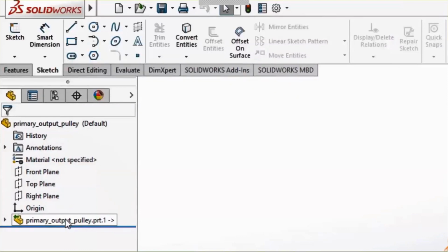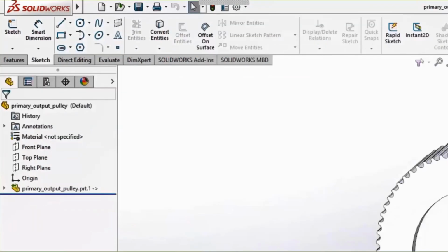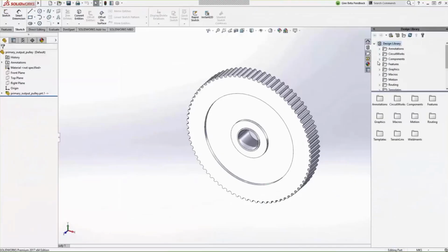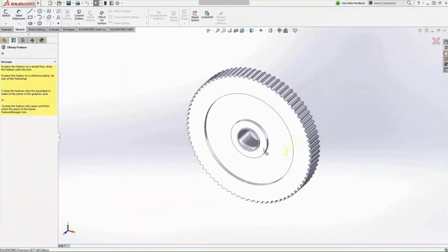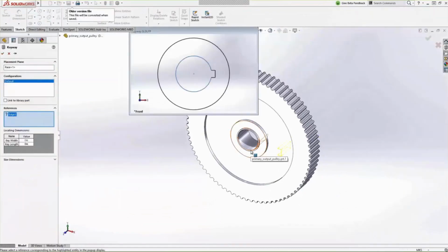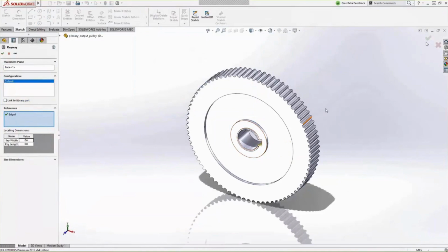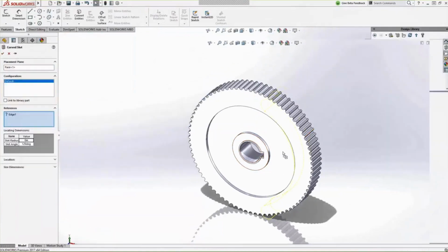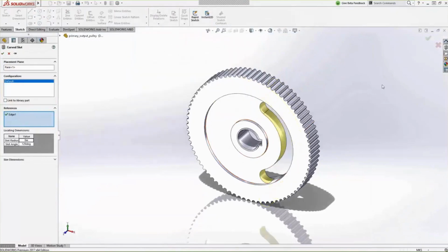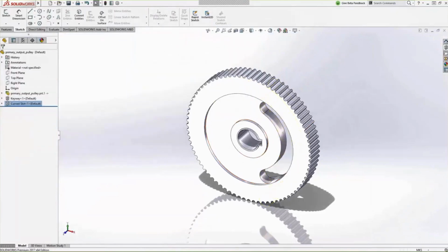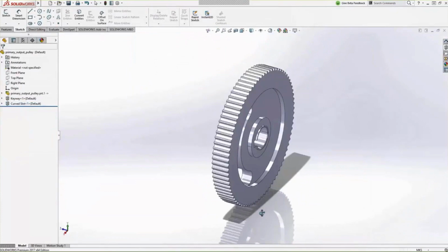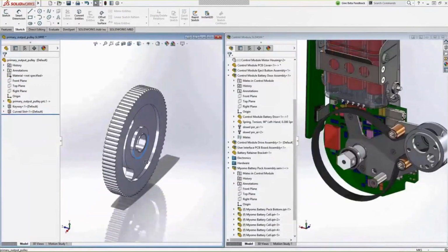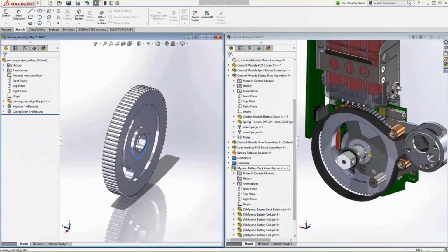Now this gear plate comes in multiple sizes, but we don't anticipate needing a change to the base geometry. We do want to do some additional machining. So from the SOLIDWORKS design library, we can drop one of our standard keyway cutouts and a radial slot. It's going to give us the correct rotational range of motion. And now we'll insert the part into the assembly and mate it in position, just like we would with any other SOLIDWORKS part.